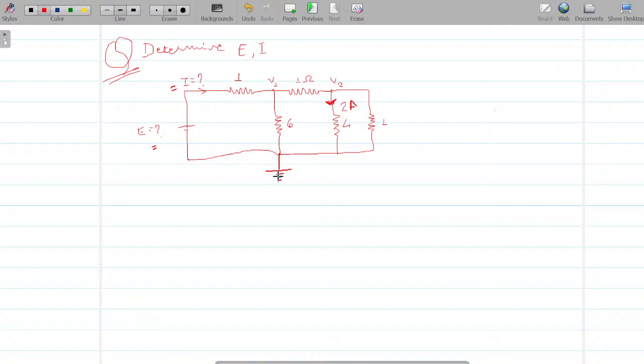Right? So when this is ground, this would be the potential with respect to ground, which is given to be V1. This is defined to be V2. This V2 would also be here because it is at the same potential because it is a conducting wire. So again, this would be V2. If this is V2, this would also be V2, right? This will be V1 because there is a resistance, otherwise this would also have V1. Now, this here is E, right? This here would be E because there is no other element barring this potential energy source that we see. So the potential here is E, right?